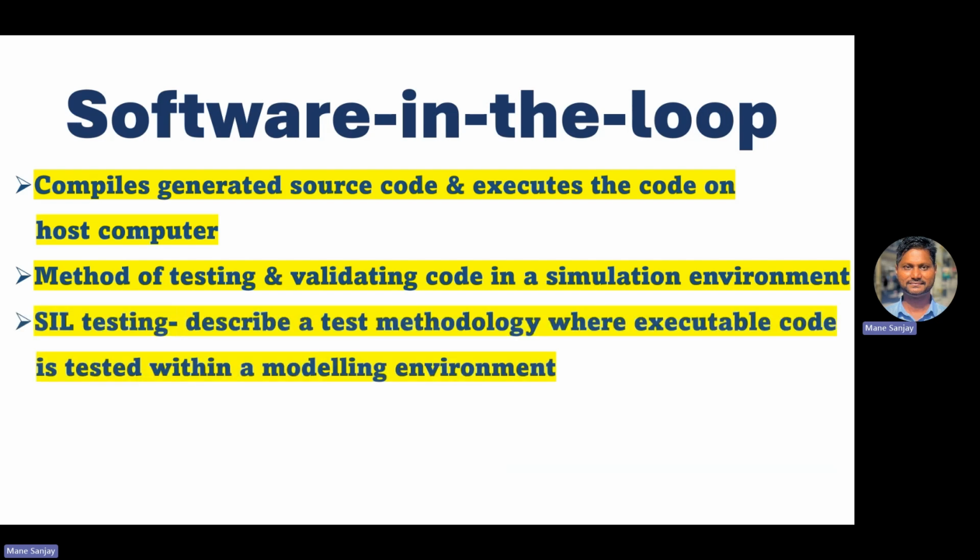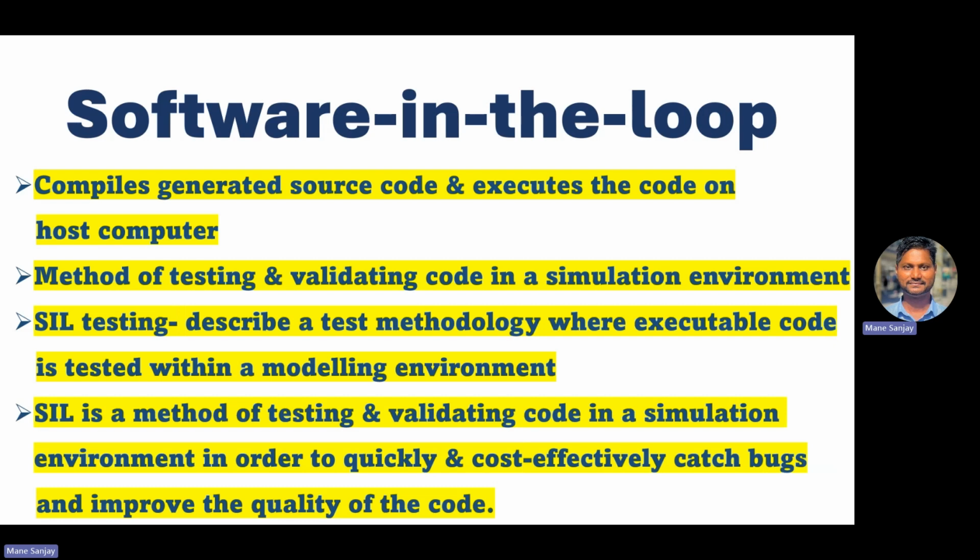The next point is, the term software in the loop testing, or SIL testing, is used to describe the test methodology where executable code, such as algorithms or even an entire controller strategy, usually written for a particular mechatronic system, is tested within the modeling environment that can help prove or test the software. That's very important. And the last point is, software in the loop is a method of testing and validating the code in the simulation environment.